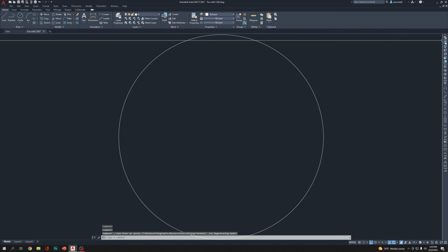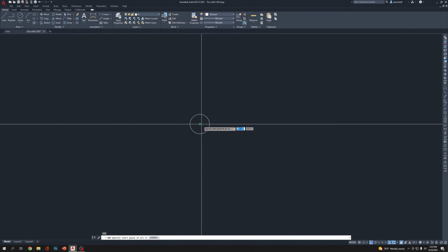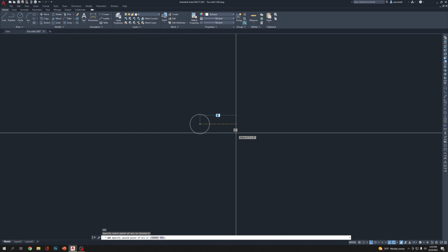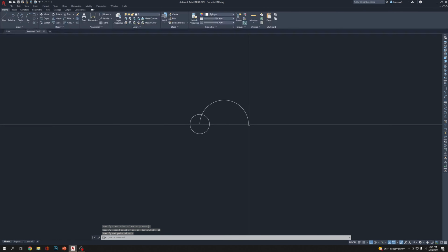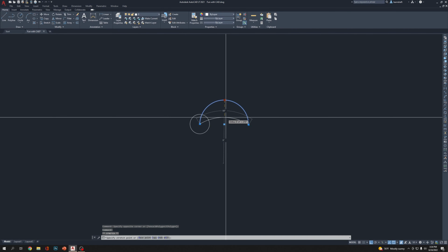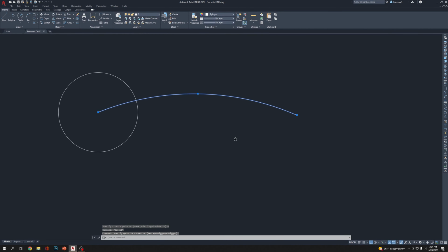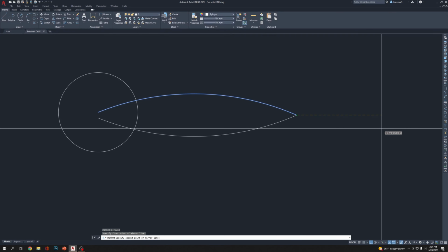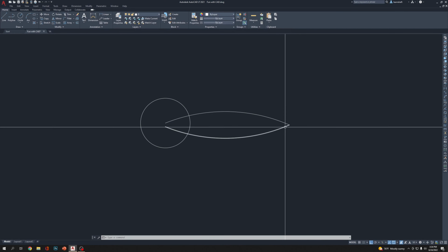I'm gonna click on my top view. It's big now. Keep it here and I'm gonna draw an arc. Click here. Go straight, let's say 10, and then click here. Then click, select and pull it down until 4 inches. So this is 4. Now I'm going to select it, mirror it, click here, click there, enter. So after mirroring, this side is closed, this side is open.